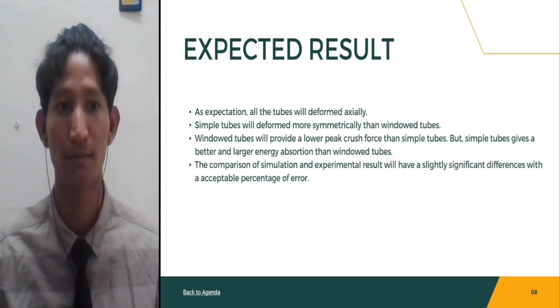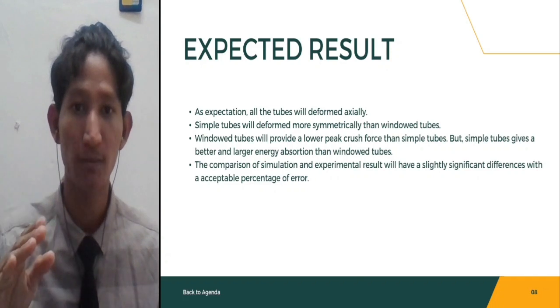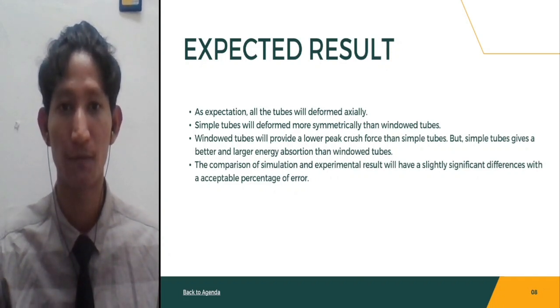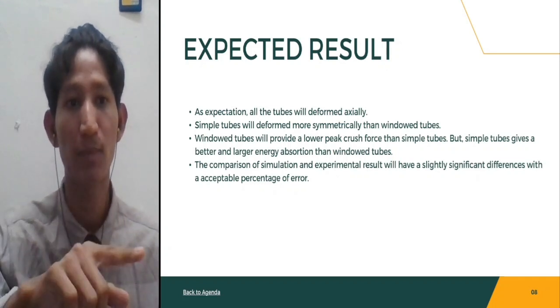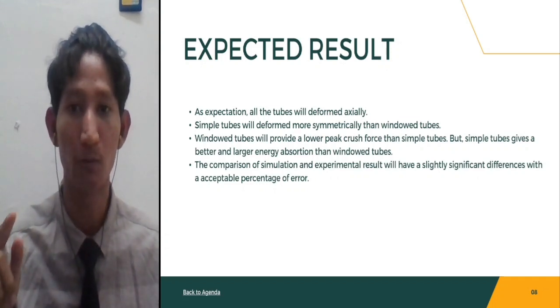Expected result. As expectation, all the tubes will deform axially as we studied for dynamic axial loading only. And then simple tubes will deform more symmetrically than window tubes.